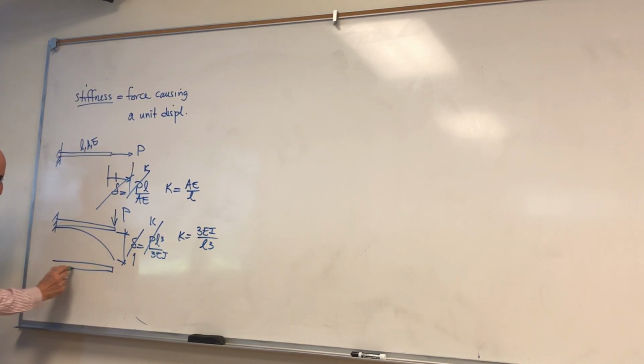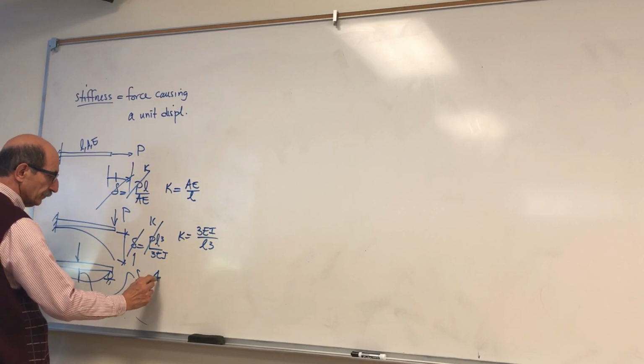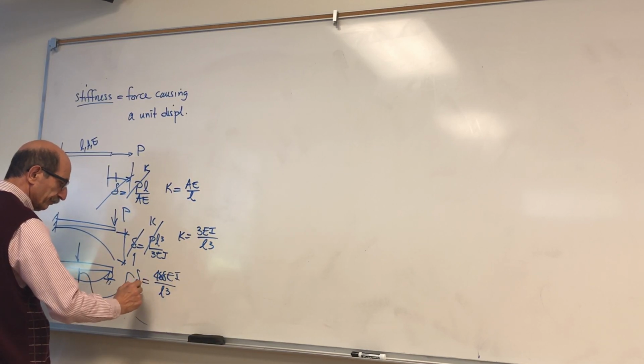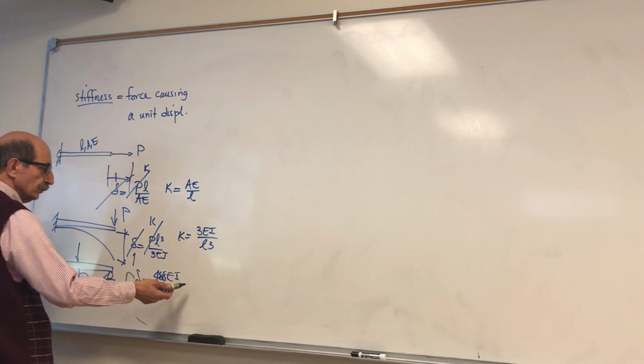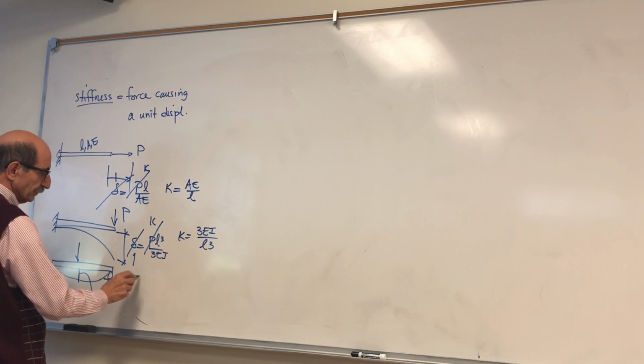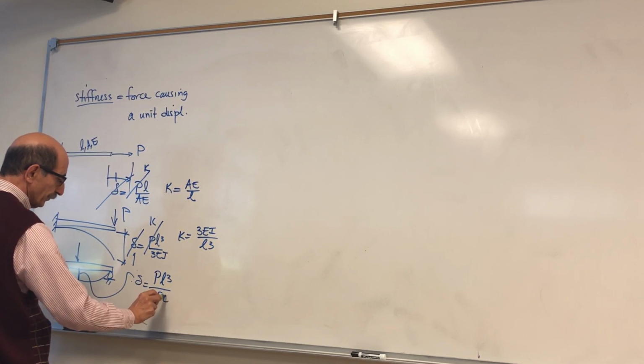If you have a simply supported beam subjected to a mass sitting here, so it's oscillating like that, and you're concerned about the displacement here under the action of load, this maximum displacement delta is PL cubed over 48EI.